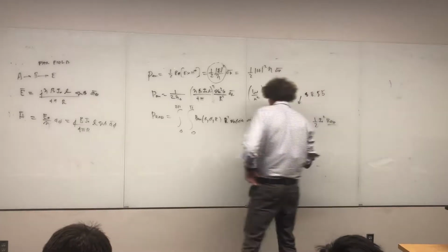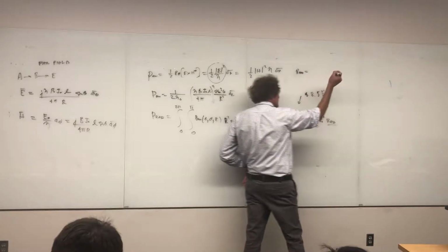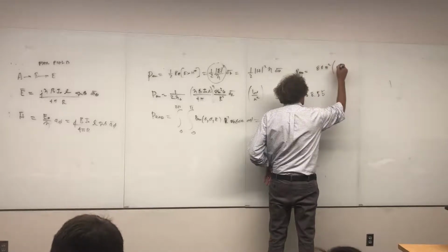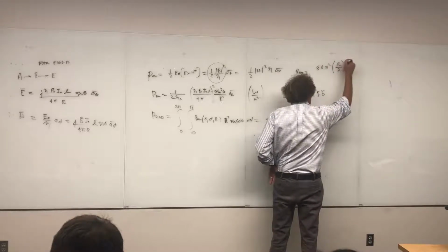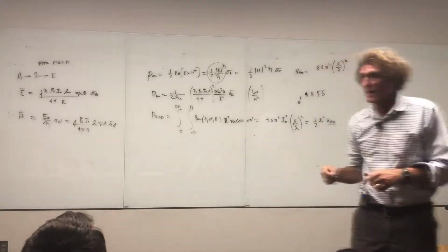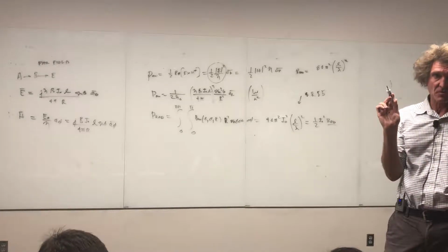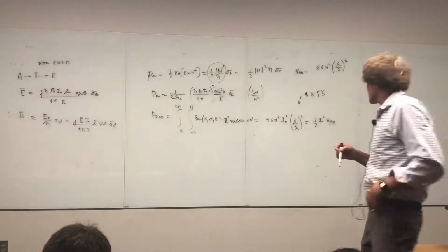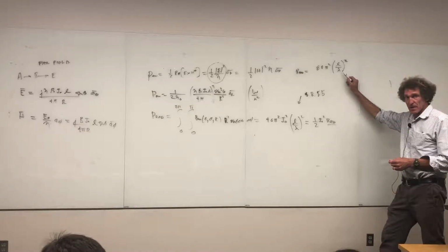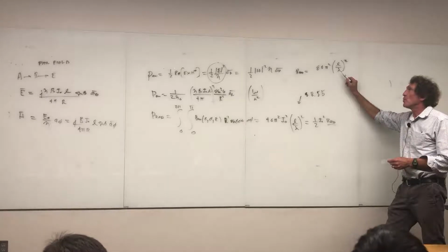What is the radiation resistance, therefore? I'll put it right here. Radiation resistance would be equal to 80 pi squared times (L over lambda) squared. Now you would like that number big, but for a short dipole, it's not big. Let's see where the limit is. If we are right at the verge where it is short, where L is lambda over 10, take a look at this. This is going to be 80 pi squared, times 1/10 squared, which is 1/100th. So that would be 0.8 pi squared.